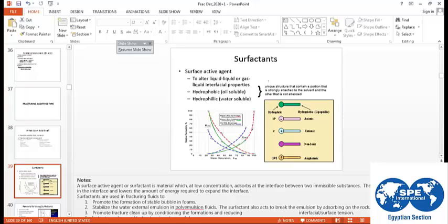So, as an example, the lighter weight proppant you select, the easier it will be carried by the gel, and it will be distributed very well inside the frac. Also, the fracture width plays a key role in the proppant distribution inside the frac. As the width increases, the proppant distribution is better. So you should apply high net pressure inside the frac to guarantee good fracture width and better proppant distribution inside the well.